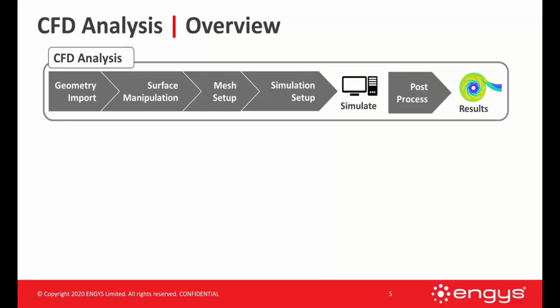So let's start at the beginning. CFD analysis has many different stages. There are challenges within each one of these. Starting with geometry import, actually we can go even before that to the geometry creation. But let me start with geometry import, surface manipulation, mesh setup, simulation setup, the actual simulation, the post-processing, and then taking these results and interpreting them and applying them back towards our designs.